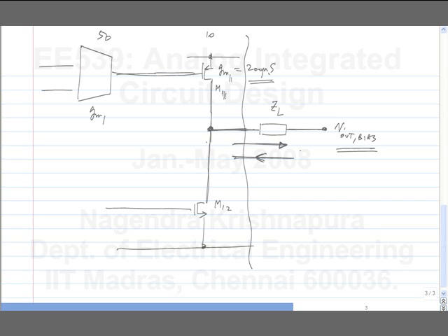It's a bias current, because this current is the difference between the current in M11 and M12. So to get the maximum current drawn out of the load, you need to have minimum value for this. So essentially, if this voltage goes very high, this almost cuts off. So the maximum current is the bias current of M12, that is I1.